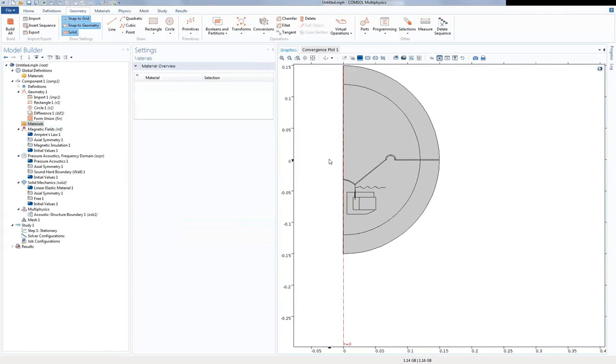half plane. The way I've worked with the geometry right now is fairly representative of what you do in loudspeaker modeling, in fact. You'll usually have a CAD file of your speaker that you will want to bring in. It's rare, of course, that this CAD file includes an air volume, so you'll add that within Comsol, along perhaps with some other details that weren't included in the CAD file, such as the baffle in this case. Now, of course, if you don't have a CAD file, you can also choose to draw the driver entirely within Comsol. Now, I've created a space for the PML to reside in.